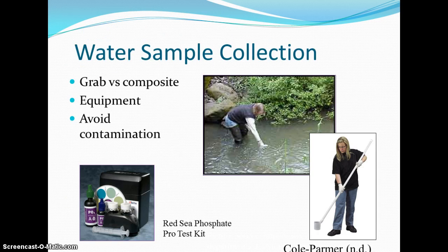Water samples may be collected either for on-site analysis or for delivery to a laboratory. A common sampling technique is the use of grab samples, which essentially means that the field team collects a sample directly from the surface water body. The field team may use the collection bottle, a long-handled dipper, or some other tool, but whatever is used must be properly cleaned and rinsed prior to collection to avoid cross-contamination.